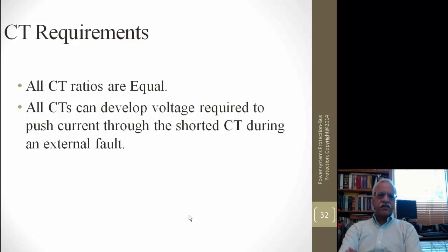What are the requirements of this? All the CT ratios are equal. This is just a general statement here. You can use multiple CTs, but there are various arrangements where you can connect the relay across the full turn, and you can use the tap ratio also. For this, there are manufacturers' bulletins and application notes. Please do refer to that. We are looking at the basic concepts here, and if you want to really apply this, you have to go through those to see how to use it if there are CTs with different CT ratios.